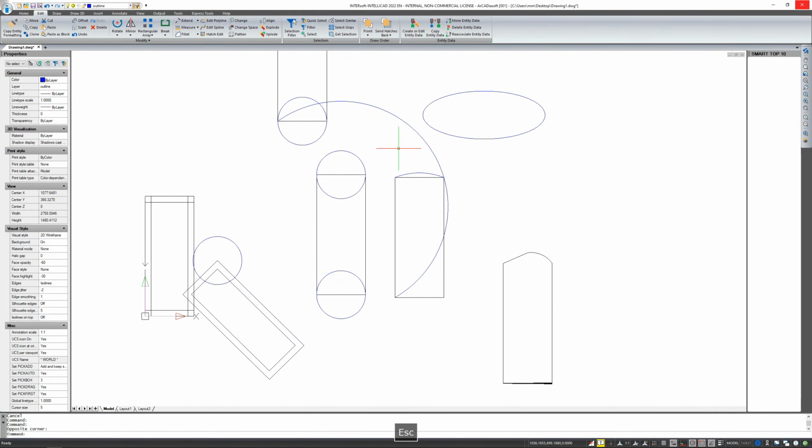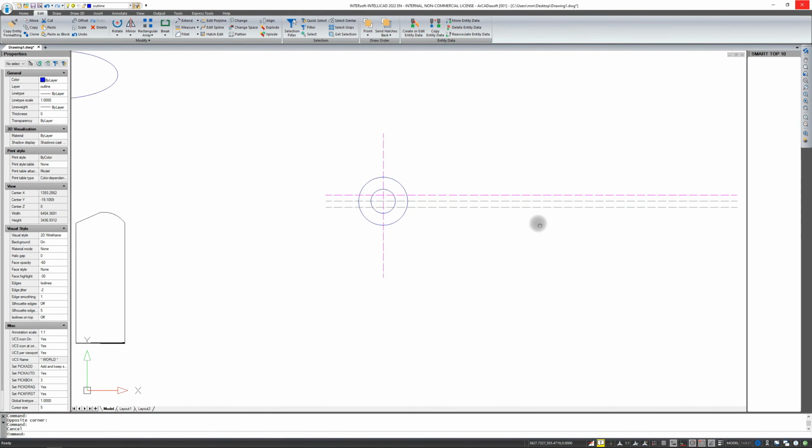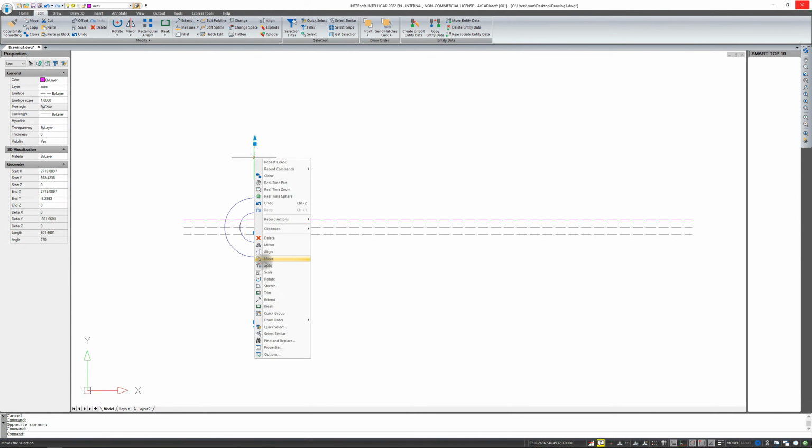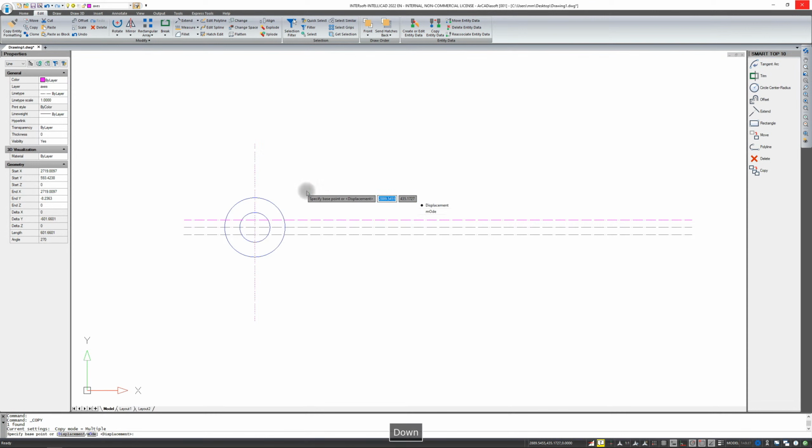Now I will show you another example of copying. Select again, right-clicking, and then Copy Options. Now you can choose the displacement option you have here under the cursor in the angle brackets. And if you press the down arrow, you can choose the displacement and say how long this copy of yours should be, right or left, up or down.